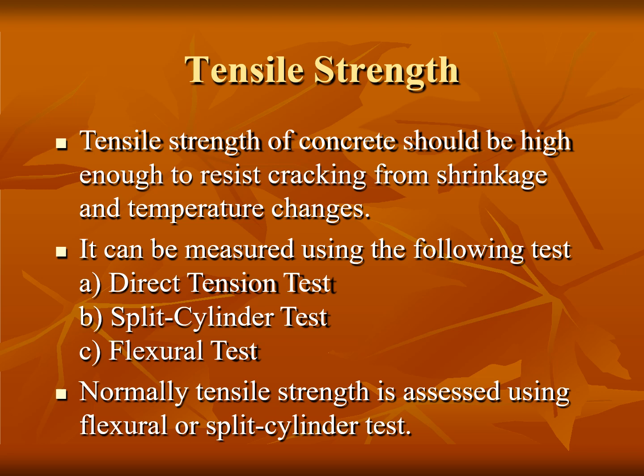Second one is tensile strength. The tensile strength is used to resist cracking from shrinkage and temperature changes. In tensile strength, three tests can be conducted. First one is the direct tension test, second one is the split cylindrical test, and third one is the flexural strength test.